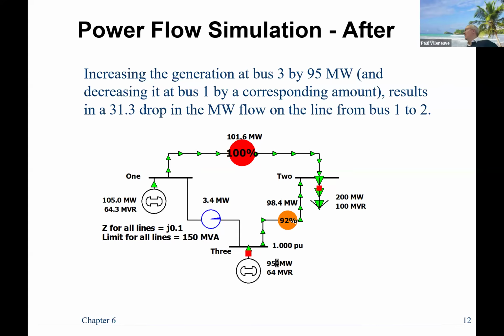So the option here is to tell this customer, sorry, I'm not going to give you 200 megawatts, which you would never do. Or you either have to run another transmission line, maybe put some generation on bus 2, a bunch of different things you can try to get that within limits. But this is what happens all the time.